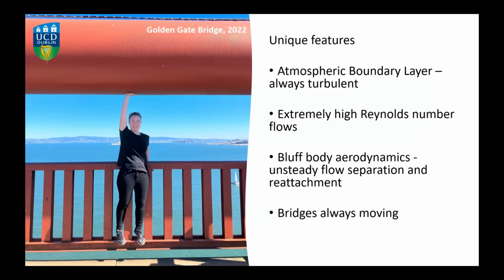Structures, the built environment, is in the atmospheric boundary layer. So everything in our world, in our built environment, is exposed to extremely high turbulence, so extremely high Reynolds number flows. And bluff body aerodynamics as a subject is not very well understood.